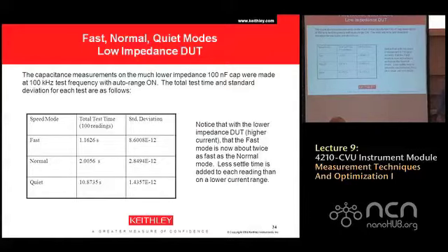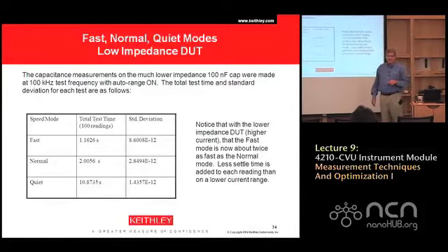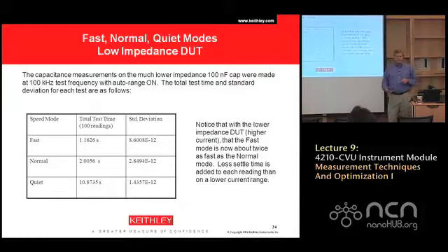Yeah, 2 digits down. So 11 milliseconds per reading to measure with 8 picofarads of standard deviation, that's a pretty fast measurement. Now this instrument, its best case is about, I think I've got it down to about 5 milliseconds per point. That's about as fast as it can process an AC impedance measurement, 5 milliseconds a point.